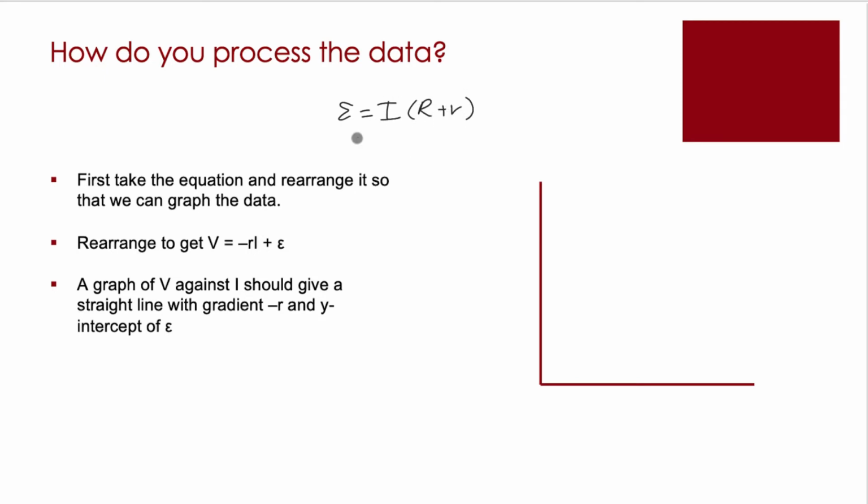If I expand that, this is our potential difference across the terminal voltage, plus I R. Now if I rearrange that and move it around, I'm going to get this potential difference, the terminal voltage, equals negative the internal resistance times the current I'm measuring, and our EMF.